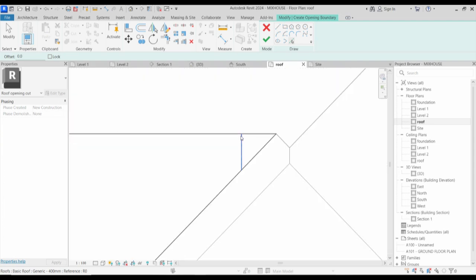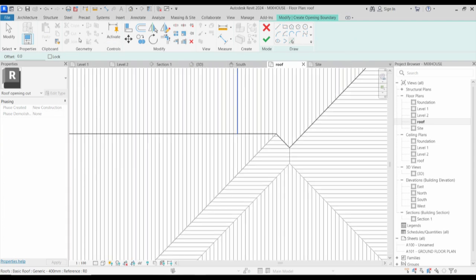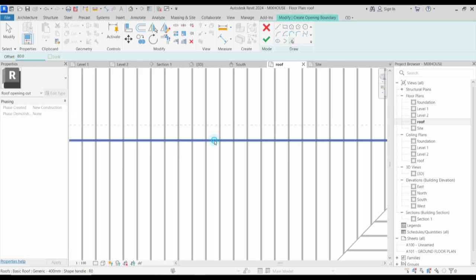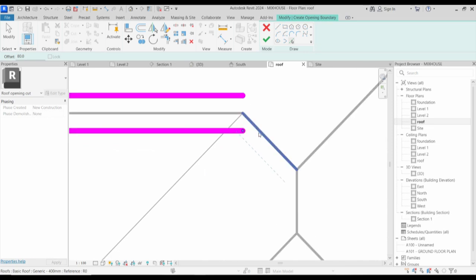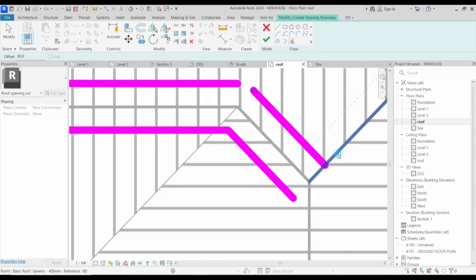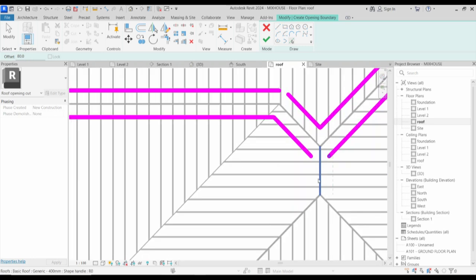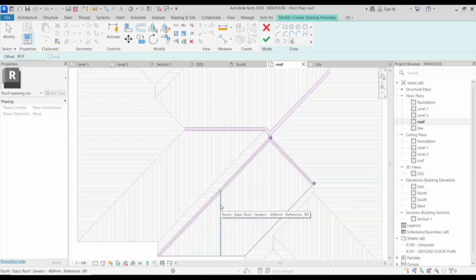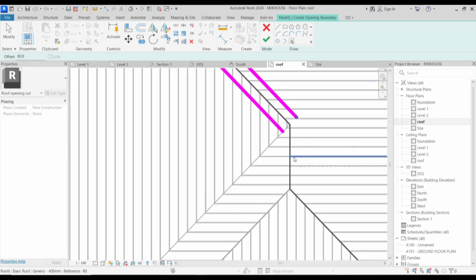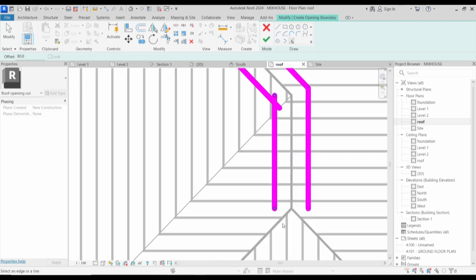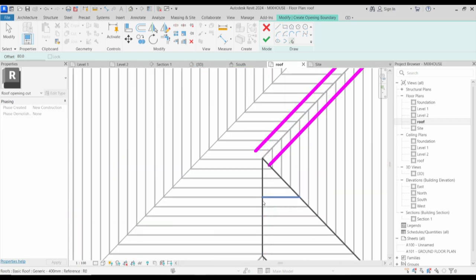So first you need to select the middle lines. Those are the things that are more difficult. So you select that. I want to set 80 millimeter as the distance from the center point. So you need to have double lines and double lines like that. Remember, it's the ridge you are doing, not the gutter, so don't focus on the gutter side. Not all the lines are ridge. You're going to focus on the main top line, and that is how you get the whole system accurate.